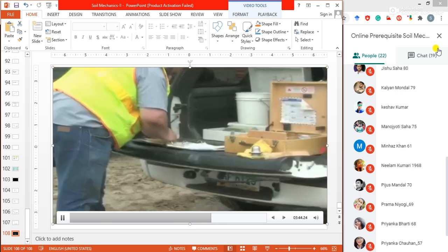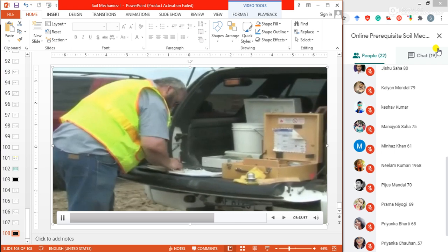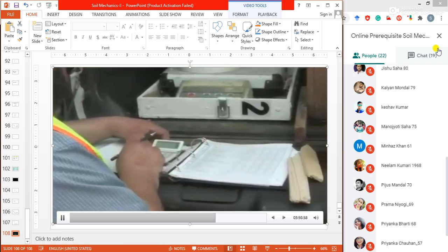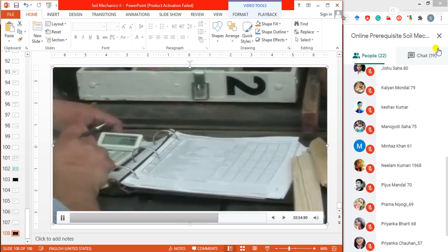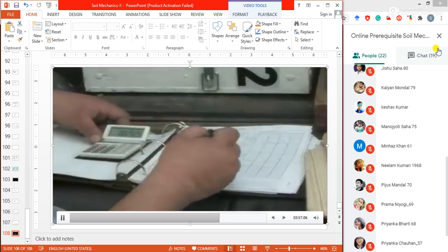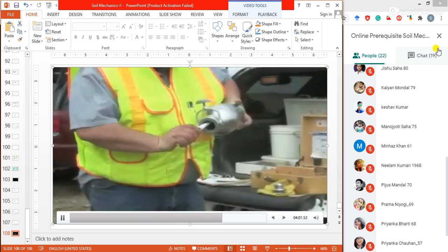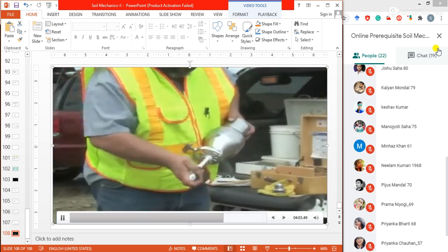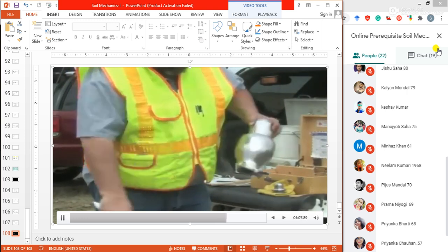The tester gauge dial reading that was recorded is the percent of moisture by wet weight and needs to be converted to dry weight. Using the number recorded from the gauge dial, obtain the moisture percent from the conversion table for the speedy moisture tester provided with the kit. Complete necessary calculations. Thoroughly clean the inside of the speedy moisture tester with a wire brush and wipe down the steel balls and cap.